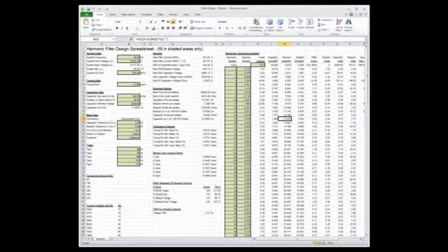And so remember, for every capacitor that you put on the bus, as you're changing it, if you're switching on more capacitance, you'll find that your resonant point is shifting all the time. So if you're going to do a staged bank of any kind, believe it or not, you're going to really need to test it for each one of those stages. If you're going to put in filters, remember, you do a staged bank with filters, you have to have a set of 3 reactors for every single one of those stages. So your cost is going to be going up dramatically.